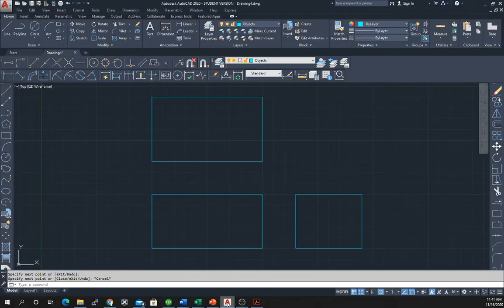So what we're going to do is we're going to use our offset, set our offset to 1, and then we'll click here and put a line in. And then we're going to do the same thing over here. Click here, put another line in, offset of 1. We're then going to use trim to delete these 2 lines and then these other extra pieces, so that we basically have kind of an inverted, flipped over L.